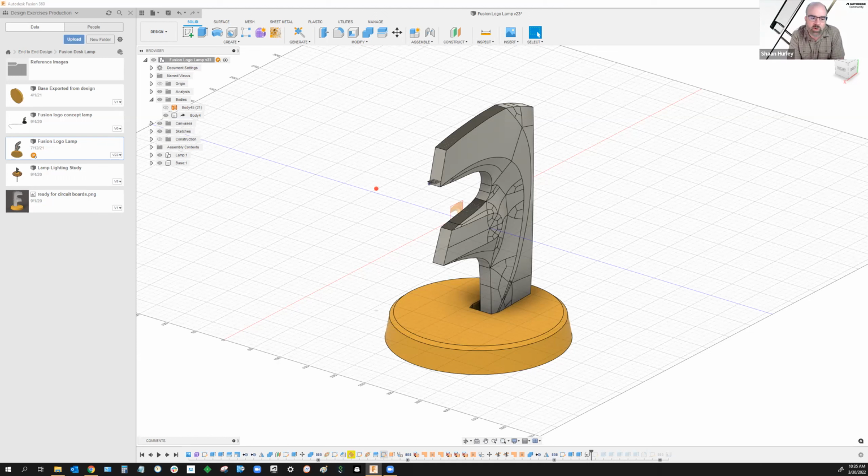Yeah, and I'll also point out that the tools that can actually rationalize scan data and figure it out, it's like the world's biggest connect the dots, right? It's like a whole bunch of mosquitoes or bugs, and you've got to figure out, is that a curve? How does that transition go? Because there may be errant points. What we call those is analytical surface reconstruction tools. And I will tell you, those tools, in my past history, are over $25,000 a seat.